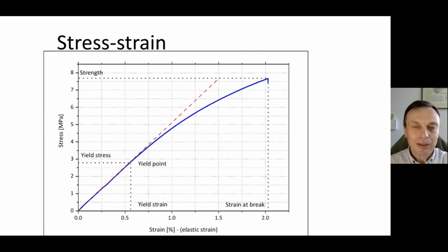The important part is, of course, the strains caused by stresses, because they can lead to damage of the material. Here you can see a typical stress-strain curve for limewood again. On the y-axis we have stress, which is generated when applying strain, when stretching the wooden sample.